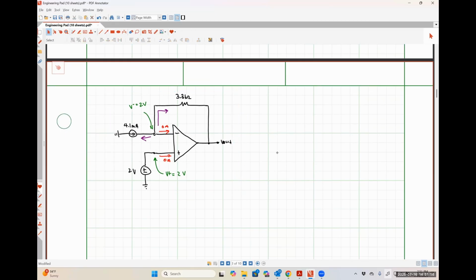So this is our original circuit. Let's look at it with VS on and CS off. Okay. So with our current source off, that is literally just going to be an open circuit over there. So we would have something akin to this.